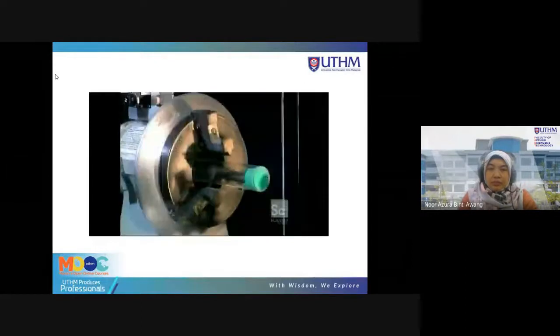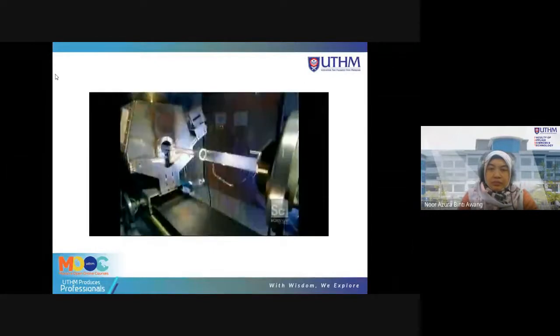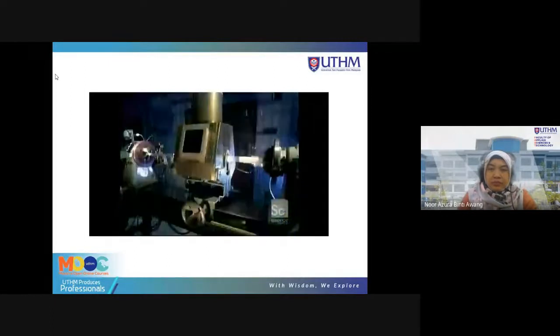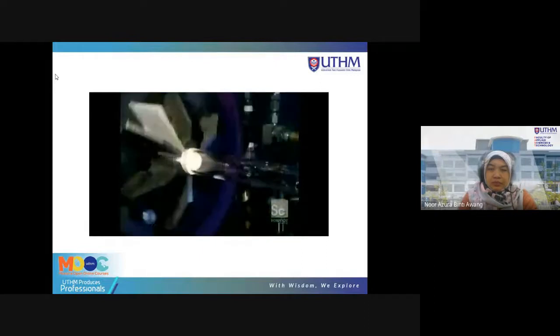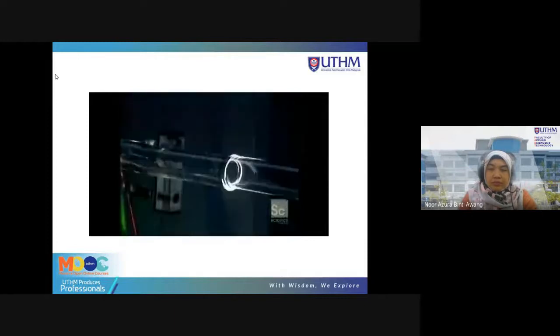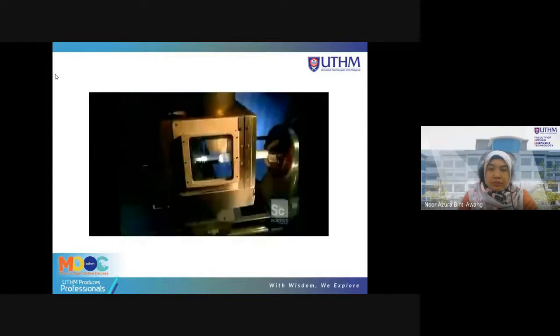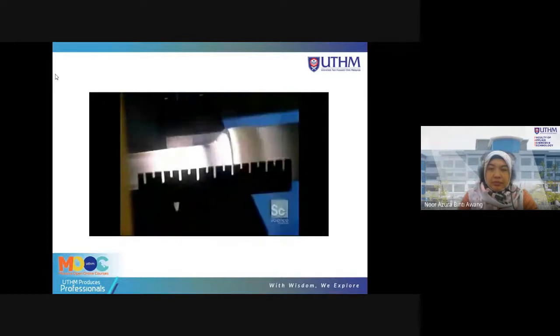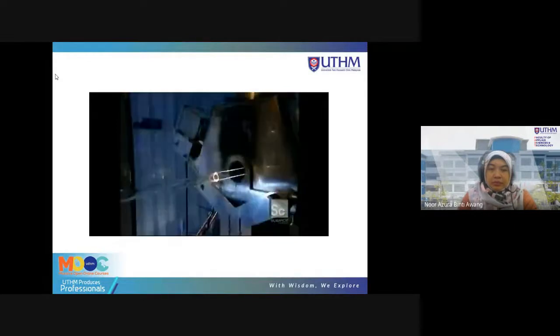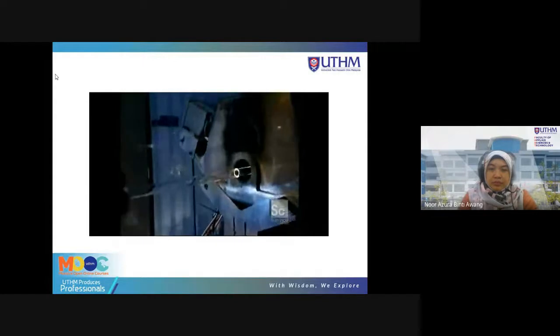As the tube spins, they inject a mixture of chemical gases inside, while a traversing burner heats everything up. The gas mixture contains liquid forms of silicon, an abundant chemical element found in nature, and germanium, a chemical element similar to tin that's used as a semiconductor in transistors and other electronic devices. As the gases heat, they undergo a chemical reaction that leaves a white soot on the inside of the glass tube. The heat fuses the soot.